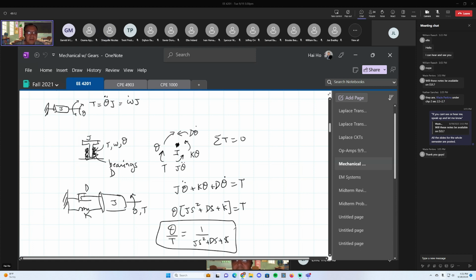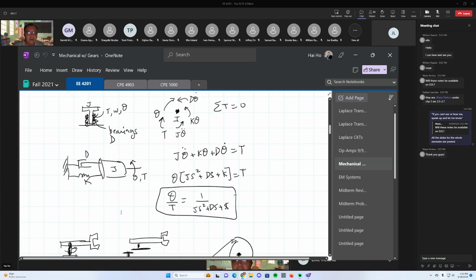So here's the schematic of a rudimentary second order rotational system. Okay, very much like the second order rudimentary system for the translational system that we looked at earlier. So you've got an inertia load with some friction, some spring constant, and there's some torque exerted on this system, and there's an angular displacement state variable called theta.